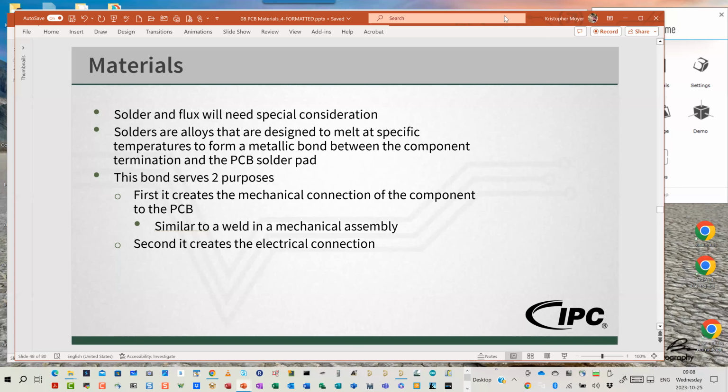is now like a 2% cost adder for each additional pair. So it becomes almost negligible if I want to change from 8 layers to 10 layers, 10 layers to 12 layers, and so on. So there's a big cost adder jump from double-sided to multi-layer. There's a big cost adder jump from standard multi-layer to sequential multi-layer, which you might have to do if you're doing HDI with microvias and so on. So that's the second big cost adder right there.